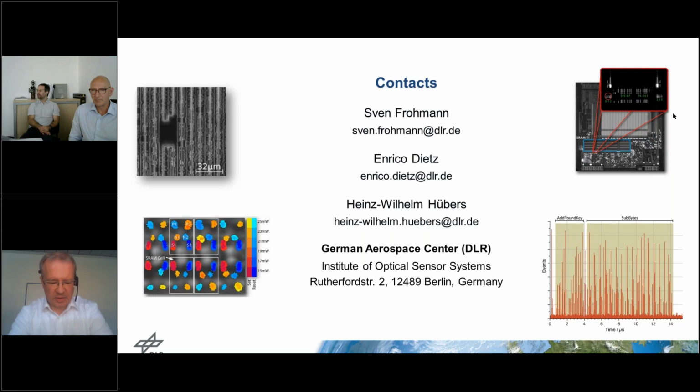Yes, as I said, our system is diffraction limited, so that means the spot size of the laser, or the spatial resolution of the photon emission, is defined by the wavelength and the numerical aperture of the microscope objective we are using. Right now, for photon emission and near-infrared microscopy it's around 1 micrometer in the current configuration. The laser spot has a smallest diameter of around 600 to 700 nanometers. We're using an objective with a numerical aperture of 0.85.